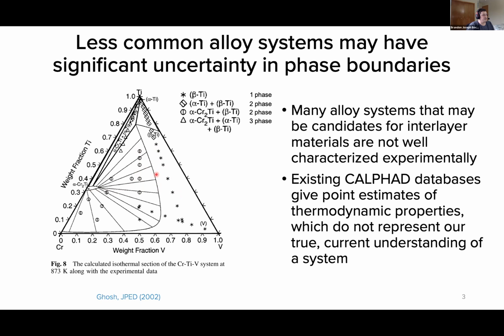In the assessment here, they chose to model between them using this data and certainly some other underlying thermochemical data. But we can see that we're not capturing some of the behavior here as you decrease the vanadium content, and experimentally we saw single phase BCC chrome vanadium titanium.